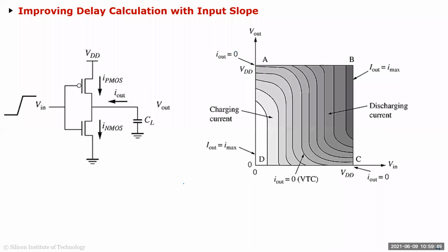All right. So if you remember, there was a lot of information on the first few days when Puneet was taking the course. He introduced some timing models in the .lib, and he said that the delay is not only dependent on the load cap and the resistance of your switch, but also on your input rise time, right?